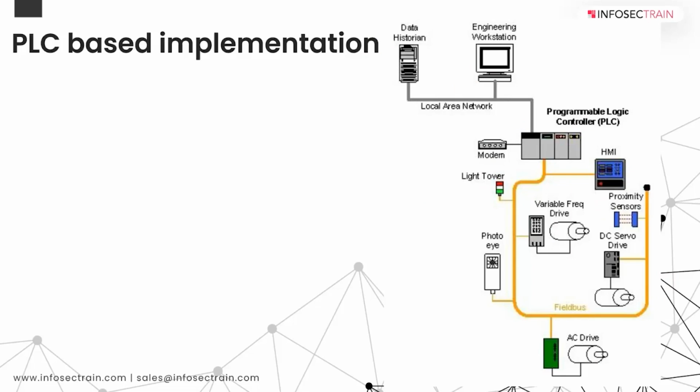So PLCs are used in both SCADA and DCS systems as control components of the overall hierarchical system. In a SCADA system, they may provide the same functionality as RTUs, but it depends on a case-to-case basis. But when we talk about DCS, PLCs are implemented as local controllers within a supervisory control scheme. In addition to PLC usage in SCADA and DCS, PLCs are also implemented as the primary controller in smaller control systems, where the configurations provide operation control of smaller processes.